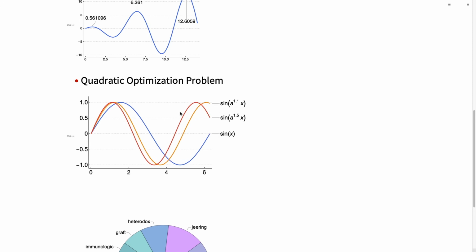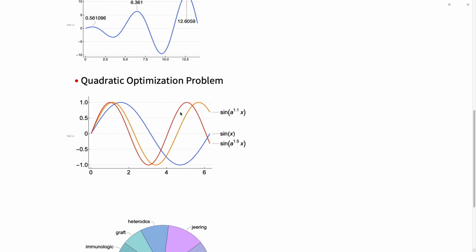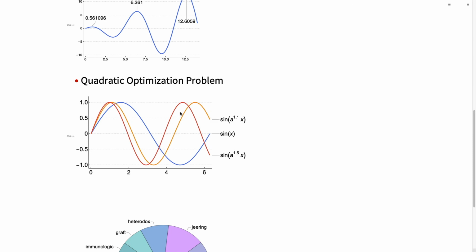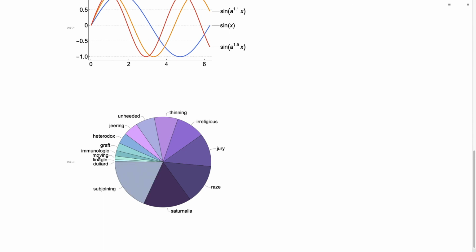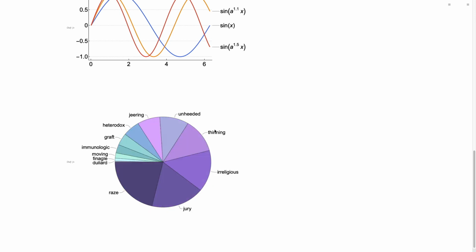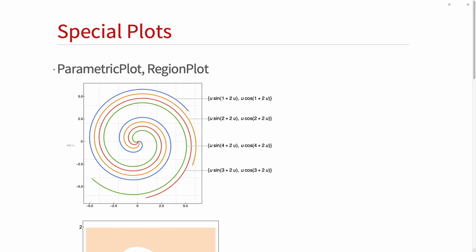Other automations, for the complex plot, it's adding some extra information about the real part or imaginary part on the labels. And you only need to specify expressions, and it will pick up the function itself. The label location for the curve, I did not do anything special to move this label. It will find the curve itself and move along it, so it doesn't run into the curve, and it doesn't go out of the plot range.